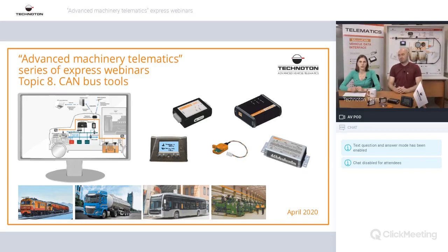For example, from the J1939 protocol to J1708, or with some specific models I will mention further, from the CAN interface J1939 to RS-232, RS-485 or Modbus. Imagine a situation: sometimes vehicles like Volvo or John Deere have two types of buses. One is J1939 and another is J1708, and they have both of them.